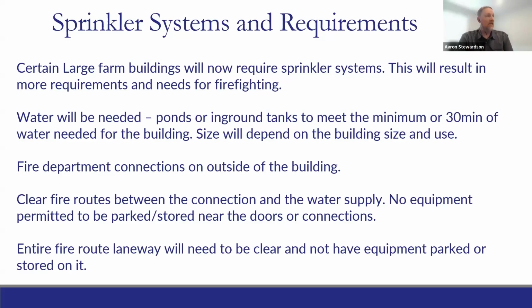You need to maintain clear fire routes between the connection and the water supply. No equipment can be parked or stored near the doors and connections. And the same thing is the entire fire route laneway must be kept clear at all times. It's no different than when you get into a larger Part 3 building, like a commercial type building, there's a requirement for a fire route out front. We've all seen that. There's no parking signs listed there. And that'd be similar for a farm building.